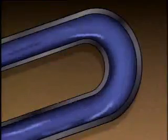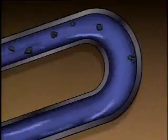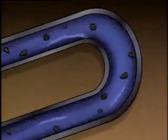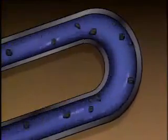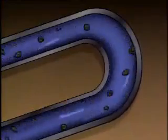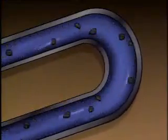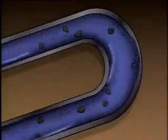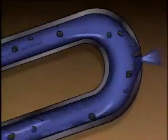Tube leakage is a problem that can seriously affect the operation of a heat exchanger. It's usually caused by the failure of a tube as a result of overheating, erosion, or corrosion. Erosion is the wearing away of tube metal caused by the flow of fluids or by solid impurities in the fluids. Some fluids that pass through a heat exchanger may contain abrasive particles. As these fluids flow through the heat exchanger, the particles come into contact with the tube metal and erode the tubes. Eventually, the tube wears away in a spot, and a leak forms.